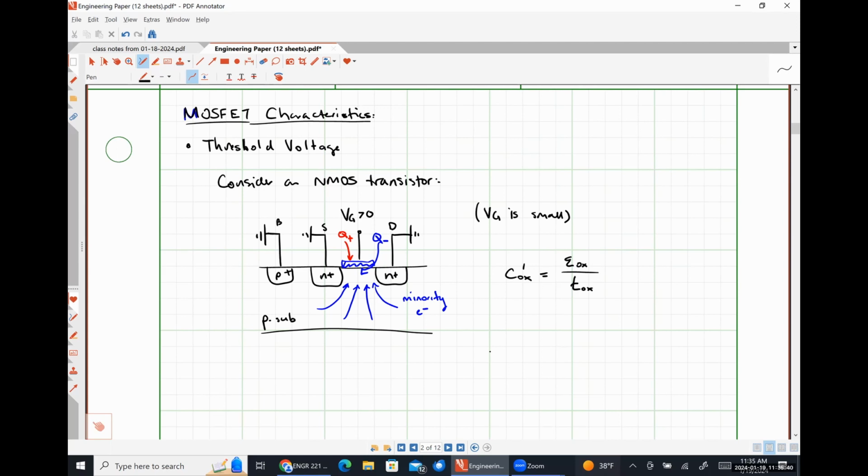So we have some capacitor thing here going on, right? So effectively, as our gate voltage gets larger and larger, we are going to attract more and more minority carrier electrons into that channel region until we hit a point called strong inversion, okay? So this process overall is called inversion because the p-type region directly beneath the gate area is gradually becoming n-type.